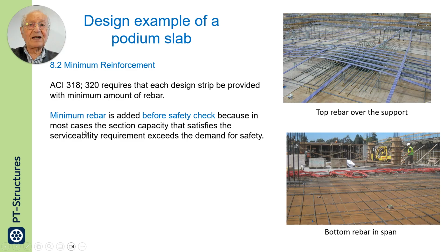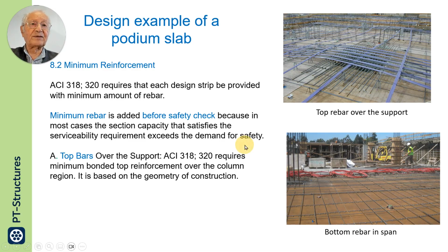Because in most cases, using ACI, the section design capacity that satisfies the serviceability requirements, we went through the serviceability requirements, satisfies the safety. So we don't have to go through a detailed safety check if serviceability already satisfies the safety also. But there are certain minimum requirements irrespective of all other steps.